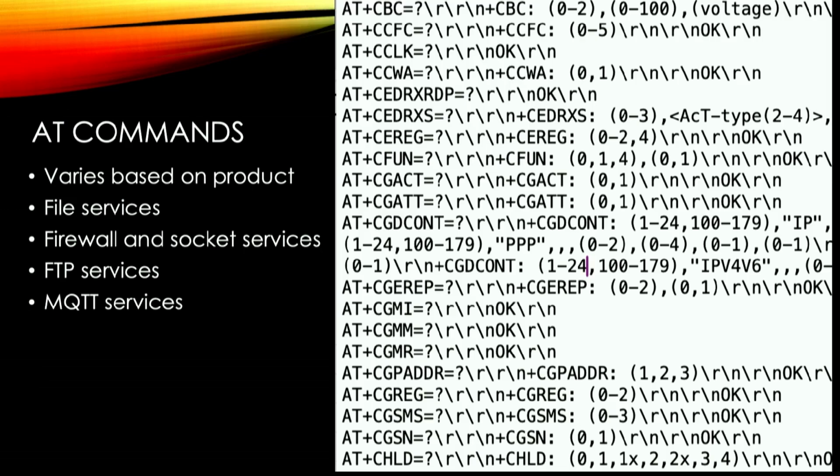And then we also created some weird fuzzing scripts. So basically you can type in the name of the command, and it'll query the device and tell you what the command structure is. You can say, oh, that's 4 variables. You say, I want to fuzz 4 variables, and it'll ask which ones you want to fuzz, and you can say, I just want to fuzz 1 and 3, and then it'll let you fill in everything with the data you want, and then you can feed a fuzz file into it to start dumping data into a particular command structure.